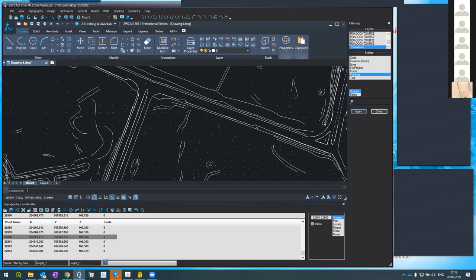So now the system, it will not take 5 to 6 minutes. I see it's much faster. Maybe in 2 minutes it will end up. So the system goes through the entire polylines, scans the entire layer, and converts each 3D polyline into a break line. It's important to us so it can affect our surface. You remember the surface that we talked about in the former lesson. Of course, I can create contours without break lines, like we did in the beginning of this lesson, sample 7. But in this case, if we do not do break lines, the contours will not be fitting. The surface will be wrongly made.